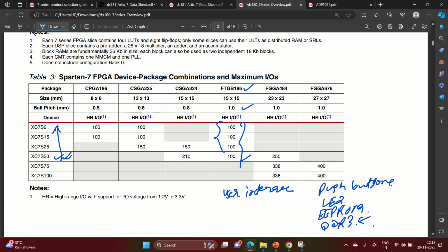At last I'll tell you how to interface this, but basically I'll recommend for DDR interface you have to have a little bit higher number of pins. For example, you can go ahead with 250 IOs or 484 pin configurations. This is much better or much suggested. All right.